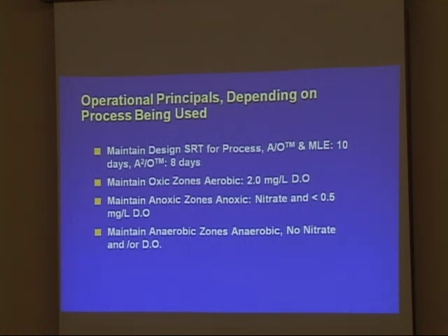Longer than 15 minutes at less than 1 milligram per liter, and that was my call off on that. And we were operating on one blower, and the lowest point when he ran that test was 45% speed, so he actually had it at the lowest, and it didn't cause any problems with the process. Granted, we weren't doing it for a long period of time, but the key thing is, you have dissolved oxygen available to the microorganisms. You gotta remember, DO is the residual oxygen that's still available for